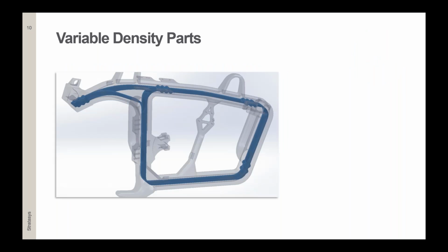Thank you, Michael. So a unique feature of GrabCAD Print is that a single part can have regions with different infill styles, and this is only possible when you're using original CAD data. If you would have to use STL files, then this possibility is not there, either using GrabCAD Print on or inside. So unlike default interior styles such as solid or sparse that are applied to the entire part, variable densities allow a single part to have combinations of solid and sparse styles.